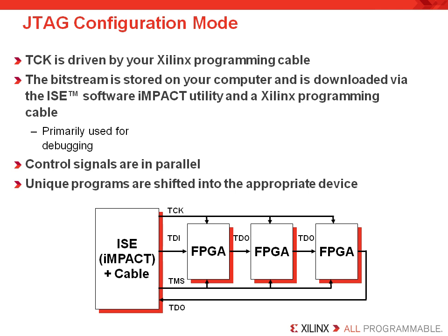iMPACT is used for file generation and configuration of Xilinx's FPGAs. The iMPACT utility is included with the ISE tools. It can also be used to program a CPLD or a Xilinx PROM and indirectly program a third-party flash component using the BPI or SPI configuration modes. Xilinx provides a number of programming cables that lend themselves to various purposes. We'll talk more about this again in Configuration 2. Just make sure after selecting a suitable cable, you have also planned for an appropriate cable connector to be available on your board. The iMPACT utility programs FPGAs through several parallel cables, including the Platform Cable USB.